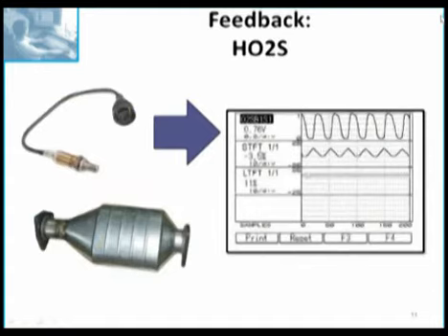Now, of course, the feedback system uses your fuel trim, and the short-term fuel trim is something that cycles basically as much as the O2 sensor. The whole goal is to put the right mixture into the catalyst for low emissions. But what I wanted to say about the short-term fuel trim is that you really can't consider it in a static moment of time. You have to consider it over time. That's when a graphing scan tool really comes into play. So if you've got a scan tool that can graph the O2 sensors and the fuel trims, you're ahead of the game because you can test drive the car and look at trends while you change the operating conditions.